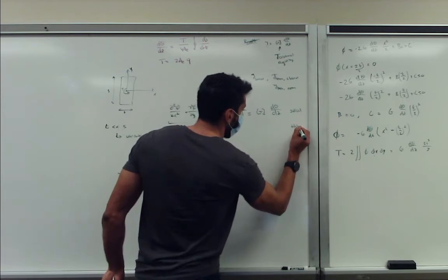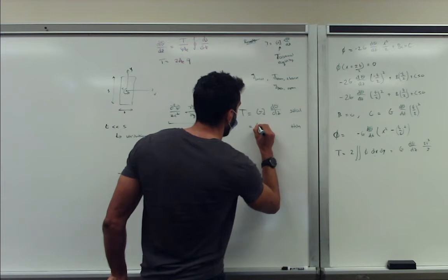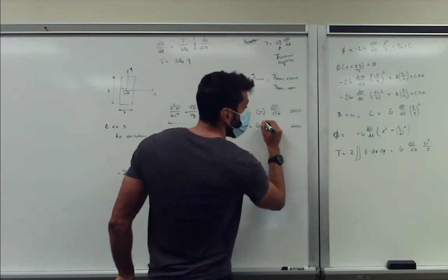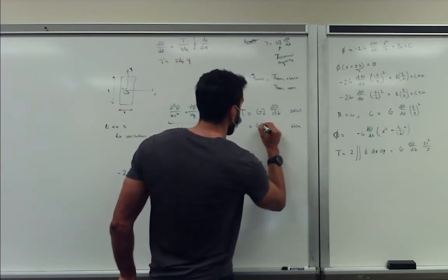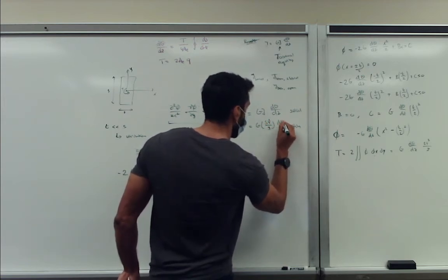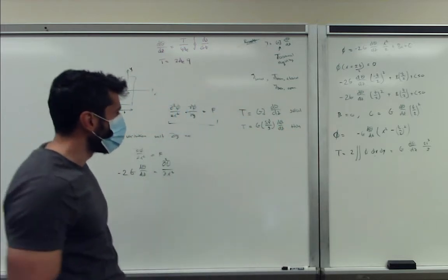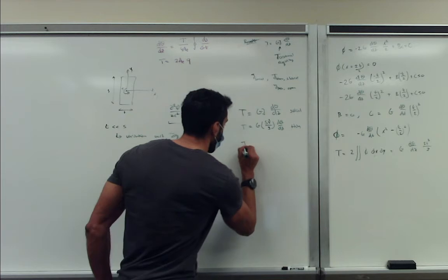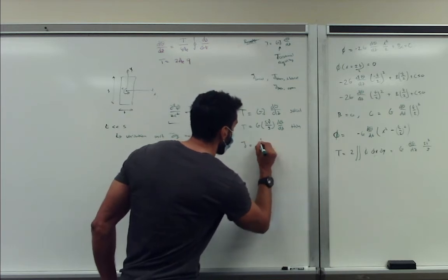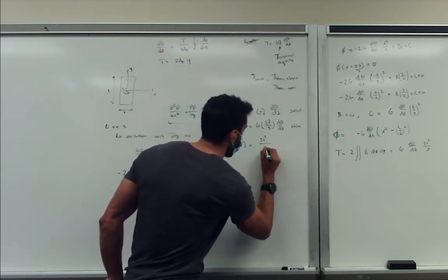And when we have a thin wall section, what we get is, let's rewrite this slightly, G d theta dz. So by comparing these two, we can conclude that J for thin wall must be equal to s times t cubed over 3.